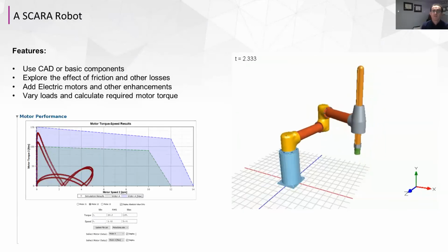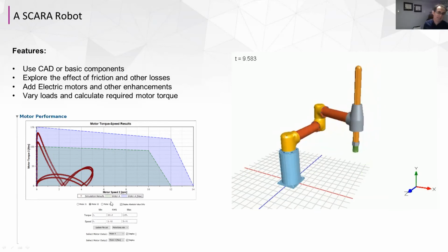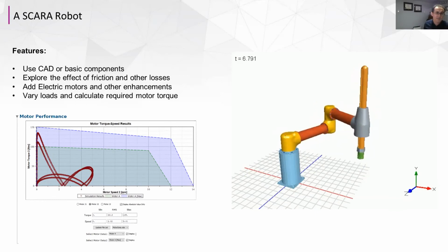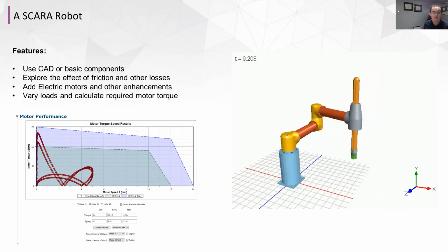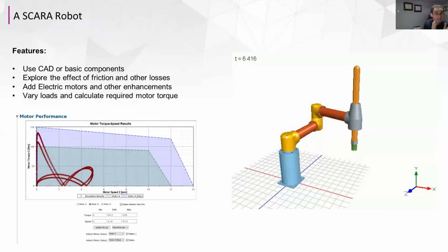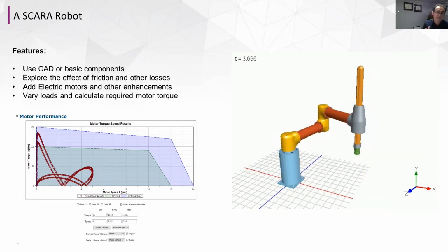Okay, here's another model. I talked about apps before for doing parameter sweeps. We can also generate customized apps. So in this case, it's a simple SCARA robot, but it's an app that allows you to walk through what are my motor torques and how do they measure up to the ranges of torques I'm allowed, the peak or the operating torques that I'm allowed for that motor, and being able to do different kinds of customized analysis. Now, again, you can build this in a Maple Worksheet inside of MapleSim, or we can bundle it and you can just look at it in an Explorer kind of context.